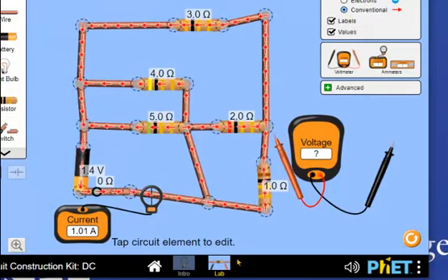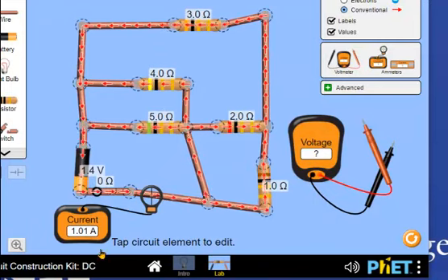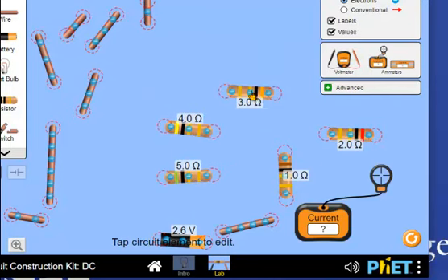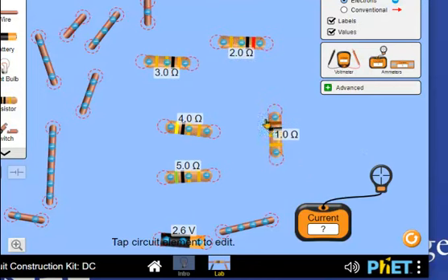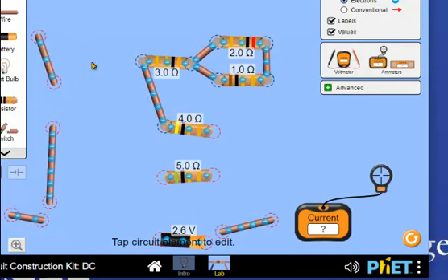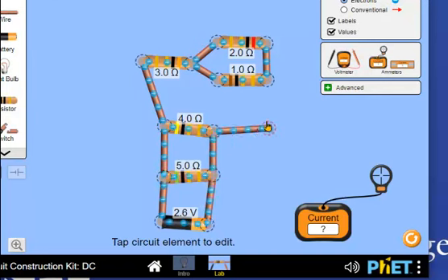Okay, now I'm going to set up the circuit diagram the way I would draw it. All right, so here we go, and again I'm going to aim for the 1.38 ohms there, respectively here, 1.4 divided by 1.01, 1.38 ohms. So I open a separate window. The 5 goes here, the 4 goes here, 3, 2, and 1 parallel up here. Connect. These guys are in parallel here, 2 and the 1. There we go. And then they connect all the way on the left here, all the way down. There and here, and I guess I need one more wire right there.